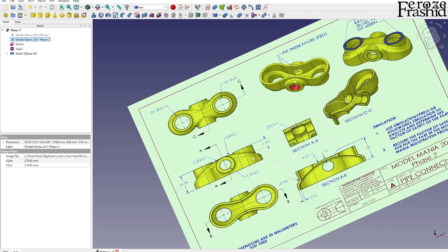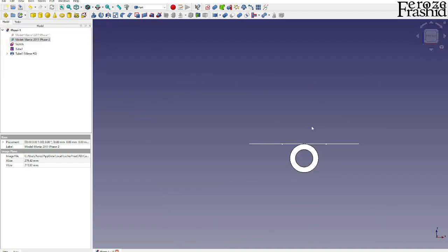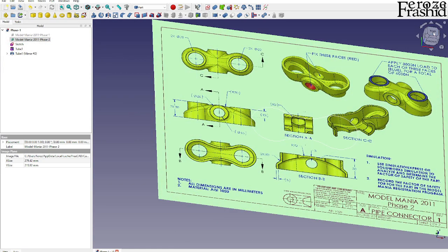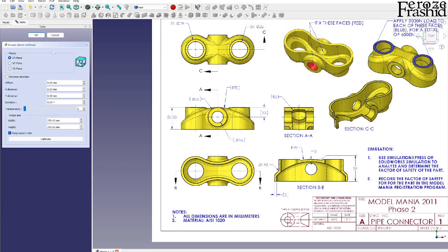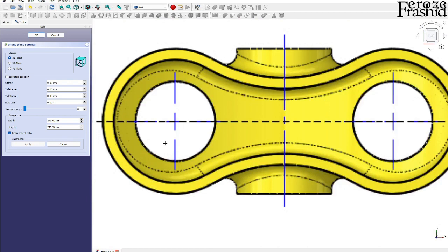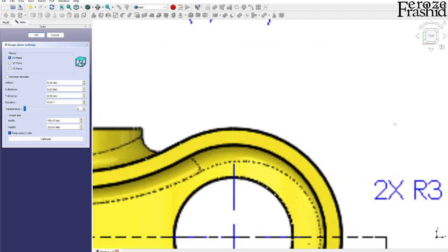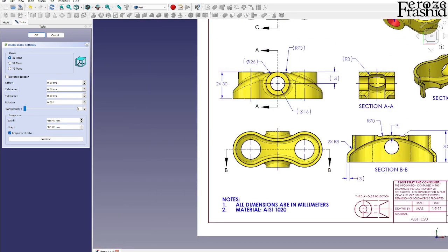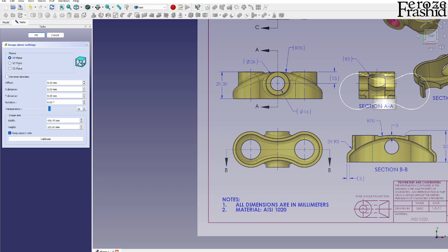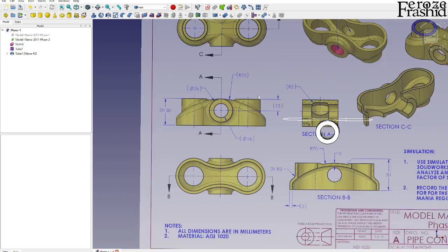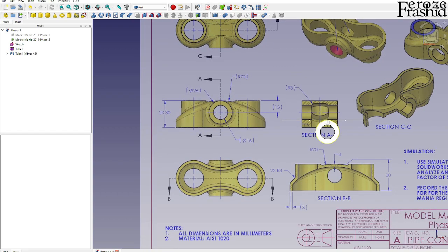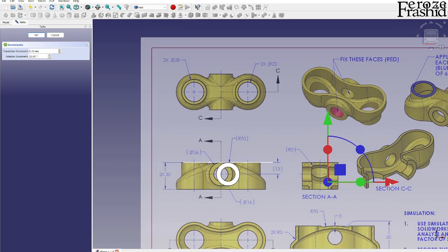Now I want to build another sketch that would look like from the side. So we want to use this image. Let's go ahead and do some processing on this. And I want to calibrate this image, so we know that the center to center distance is 60 real quick. And then I want to make it half transparent, and I want to place it on the front face. There it is. And now I want to relocate this image to match with this existing sketch.